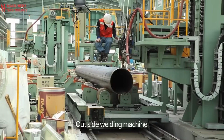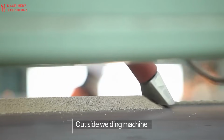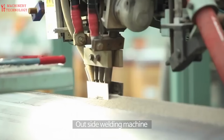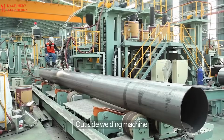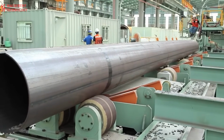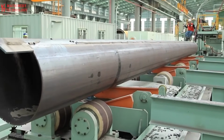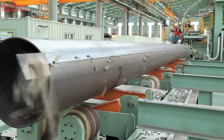Electric-resistance welded, ERW. This method involves passing a rolled sheet of steel through two weld rollers. The weld rollers have a groove around their circumference, through which the steel roll passes. There is a contact at the roll seam that transmits electricity at a high enough current to weld the seam closed. The resulting weld is very small.